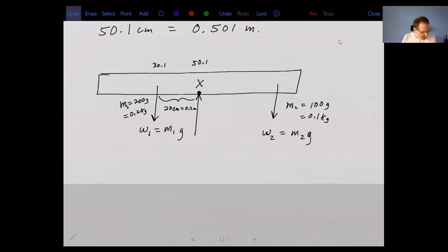And when I did this experiment, I found that it balanced when it was hanging at 90. So the first thing you have to do is calculate this distance, which we're calling L2, which is really just the moment arm. If this is the line of action of the force, then that perpendicular distance is my moment arm. So L2 is just my moment arm. That's the first part of the question, to calculate that particular moment arm.